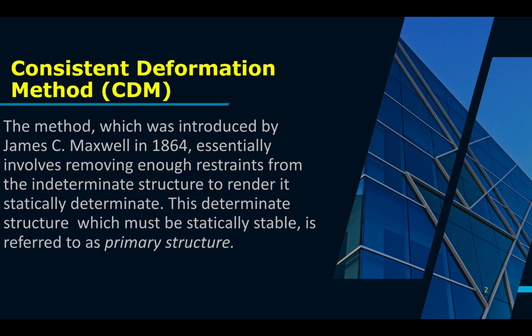The excess restraints removed from the given indeterminate structure to convert it into a determinate primary structure are called redundant restraints. The reactions or internal forces associated with these restraints are termed redundants.